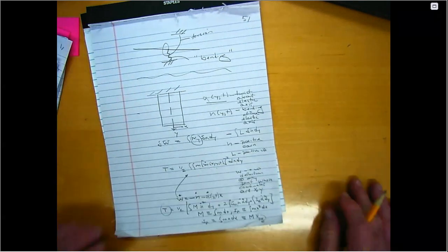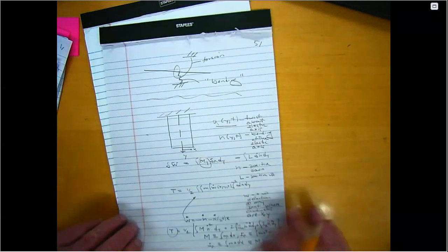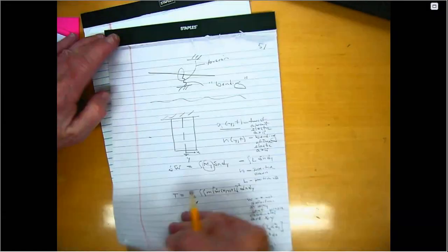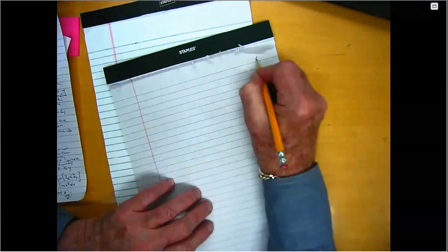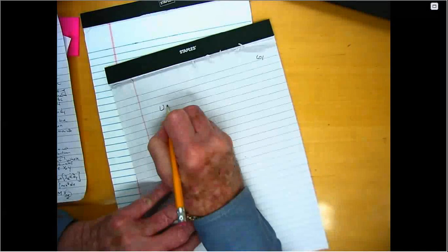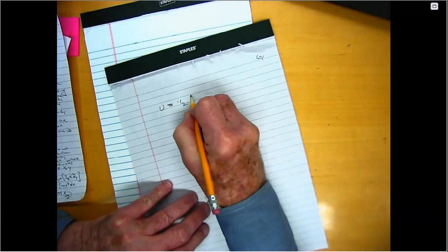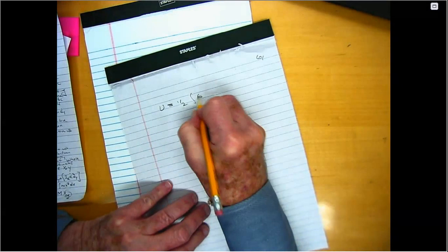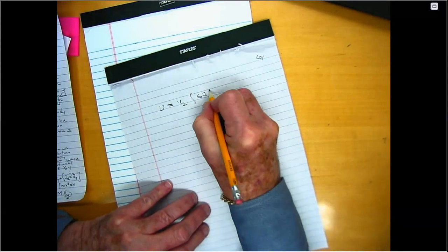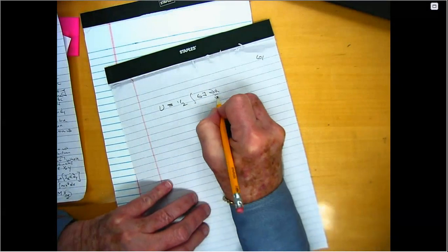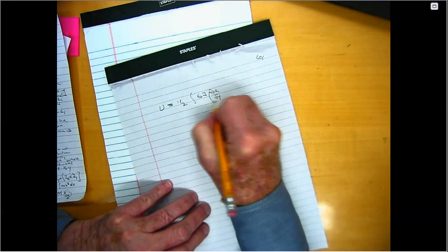Okay. So now, finally, we're now going to do the flutter analysis. But finally, we'll have to write an expression for U. And U before was 1/2 the integral of GJ, now I'm going to write it as the partial of alpha with respect to y squared, dy.